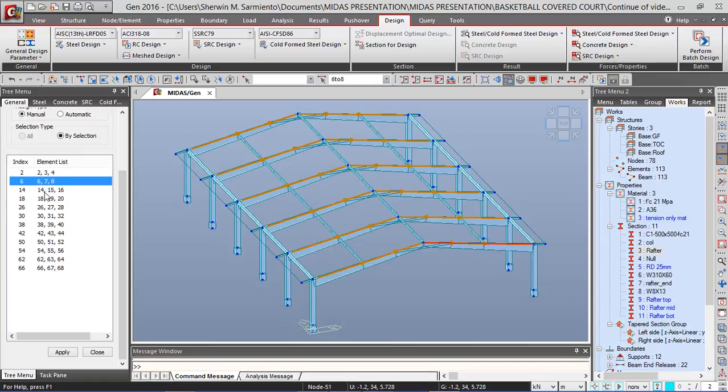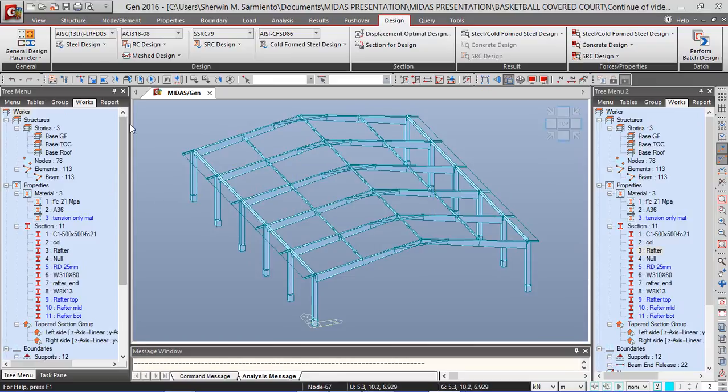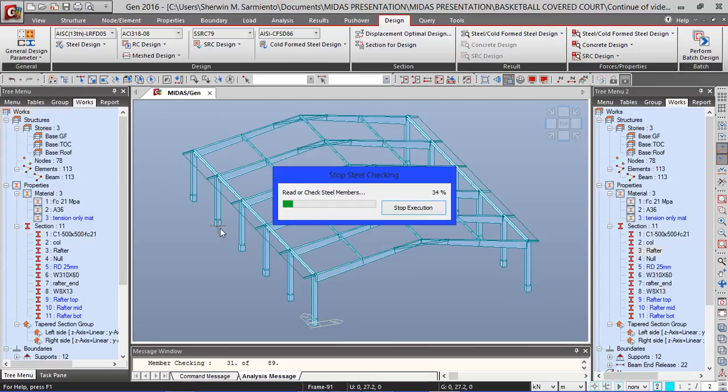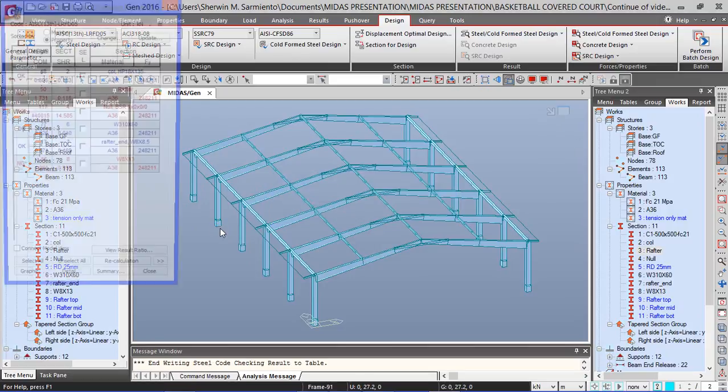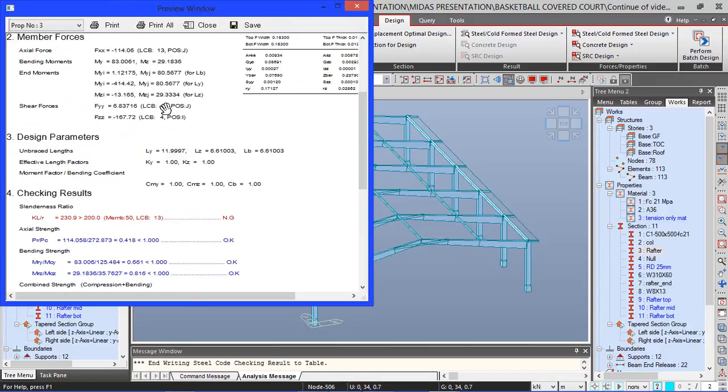And after that, I will make it into a section. So, like I said earlier, I will make these sections so that Gen knows that this whole section is one member. So, as you can see, this section here is now one member. There you go. So I can close that and you can run the analysis.